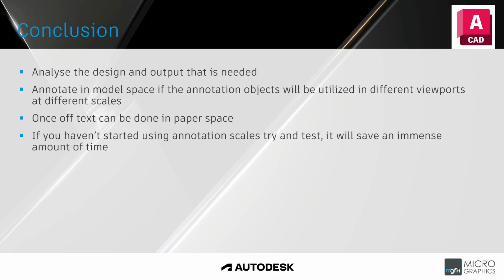So yes, it can be done, but once again, there's a little bit more work. So if you're going to be changing your scales for the viewports quite a lot before you get to the final design, or the design's still going to change by the sizing, then take a look at dimensioning everything in model space, and then creating your viewports and setting everything to annotation scales, so that if you do have different scales for your different viewports, everything is there.